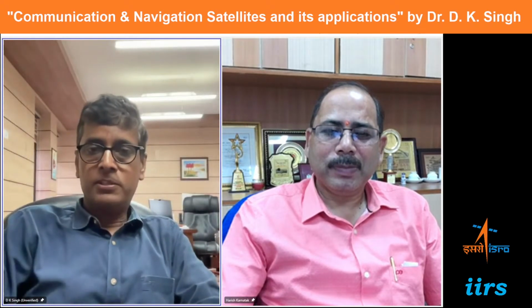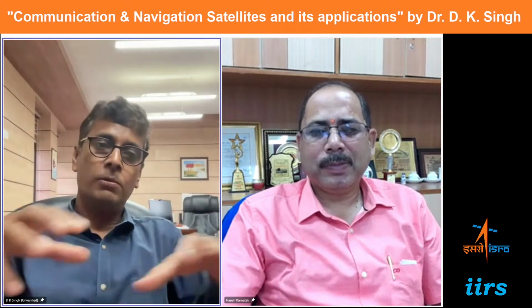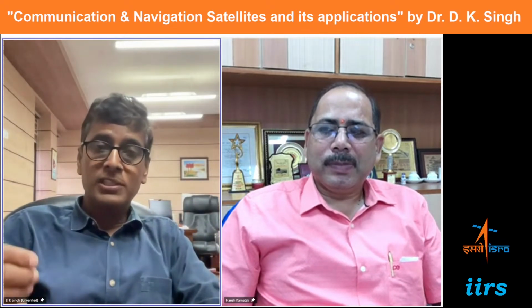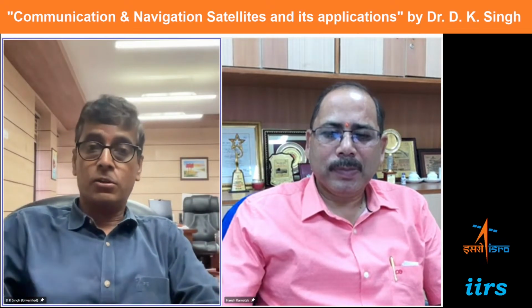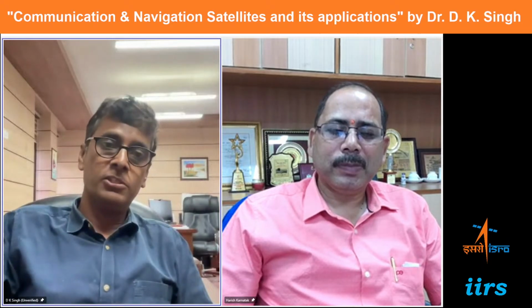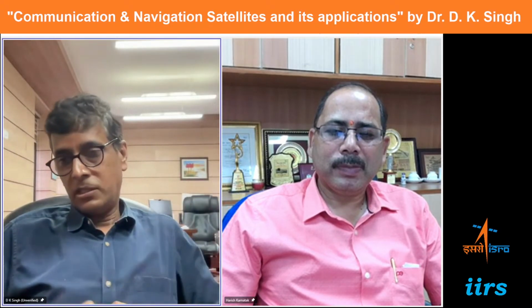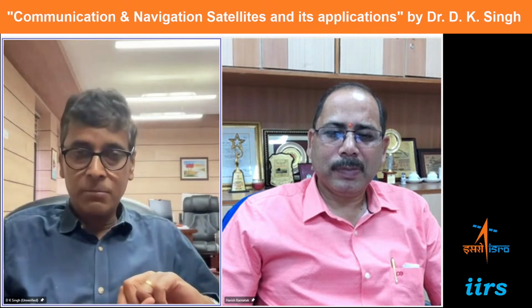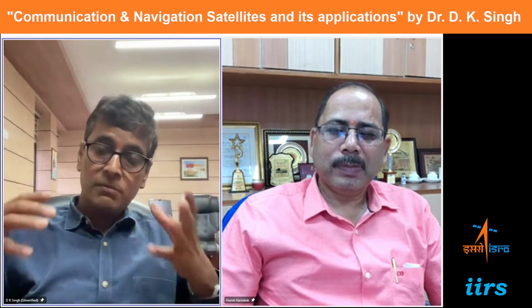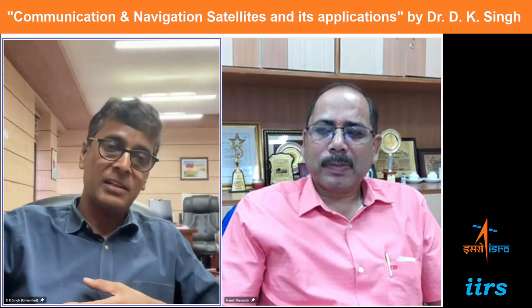the pointing is fixed. Now let us say my pointing is not fixed. I want to cover this side today, that side tomorrow. Then we design a different kind of radio frequency antenna, which uses a phased array concept, where we have multiple radiating elements. They are combined actively, and a digital computer controls the radiation from each element, so we can swing the beam wherever we want. So the choice of antenna design depends on the coverage, on the frequency at which I am operating, on the size, volume and space available on my satellite, and many other things.